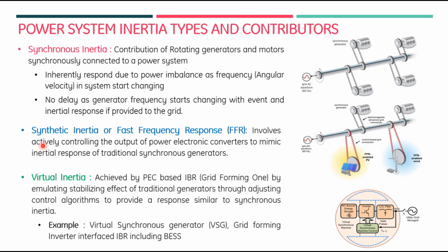Grid forming inverters have their own internal voltage source, and they see the system voltage and what angular changes there are. Based on that, they try to provide a similar kind of response to what the synchronous inertia is providing.